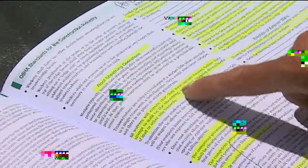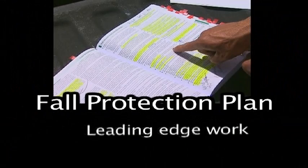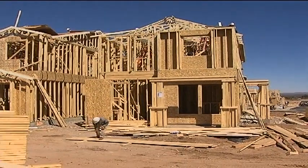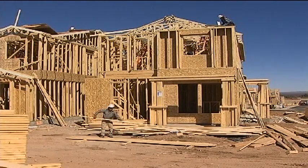A fall protection plan is only available to employees engaged in leading-edge work, precast concrete erection, or residential construction work where it is infeasible or creates a greater hazard to use conventional fall protection equipment.